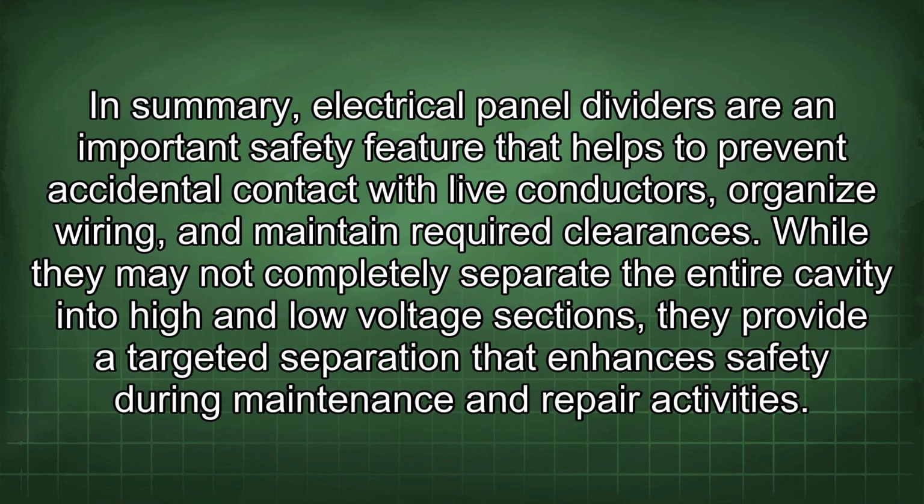In summary, electrical panel dividers are an important safety feature that helps to prevent accidental contact with live conductors, organize wiring, and maintain required clearances. While they may not completely separate the entire cavity into high and low voltage sections, they provide a targeted separation that enhances safety during maintenance and repair activities.